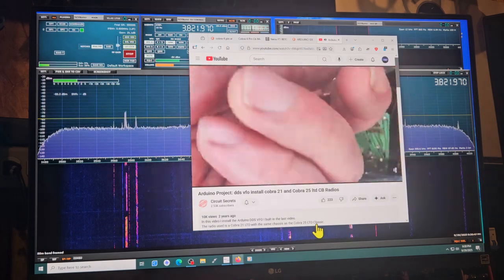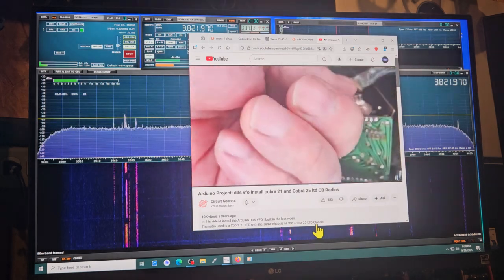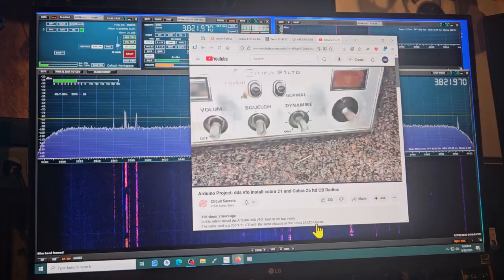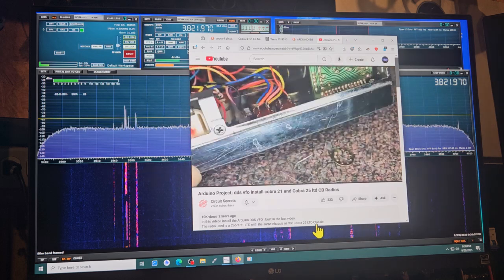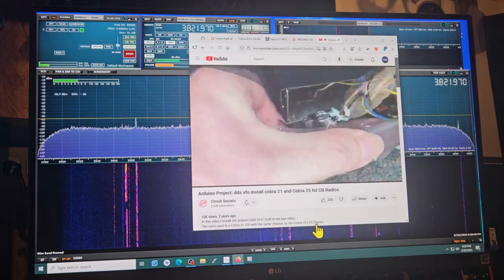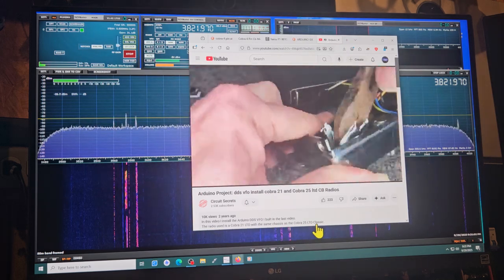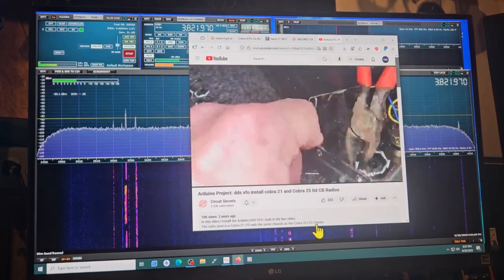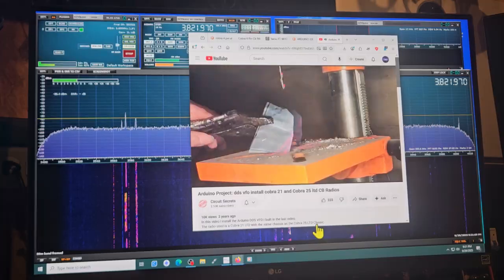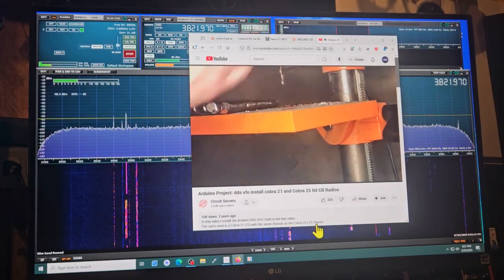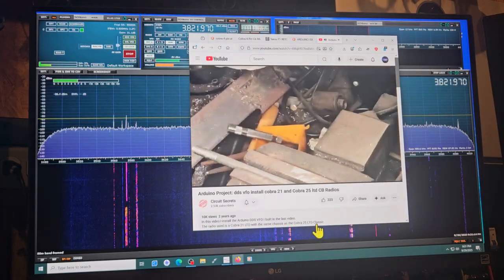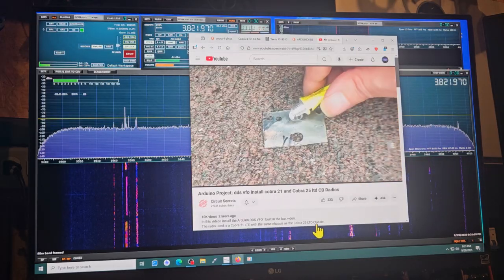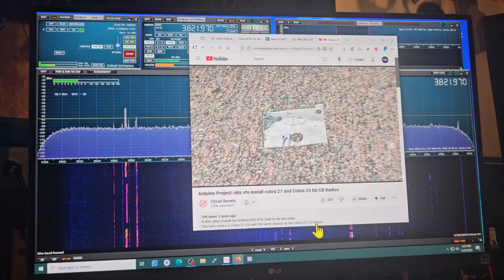First I will remove the channel selector and display. Next, I cut away the mounting surface for the channel selector. You really do have to remove a lot to get that thing to fit in there, and there really is no good way to do it. This acts as a display retainer for the OLED and the mounting point for the encoder. I cut a piece of an old mouse pad as a flexible backing pad to hold the OLED in place.